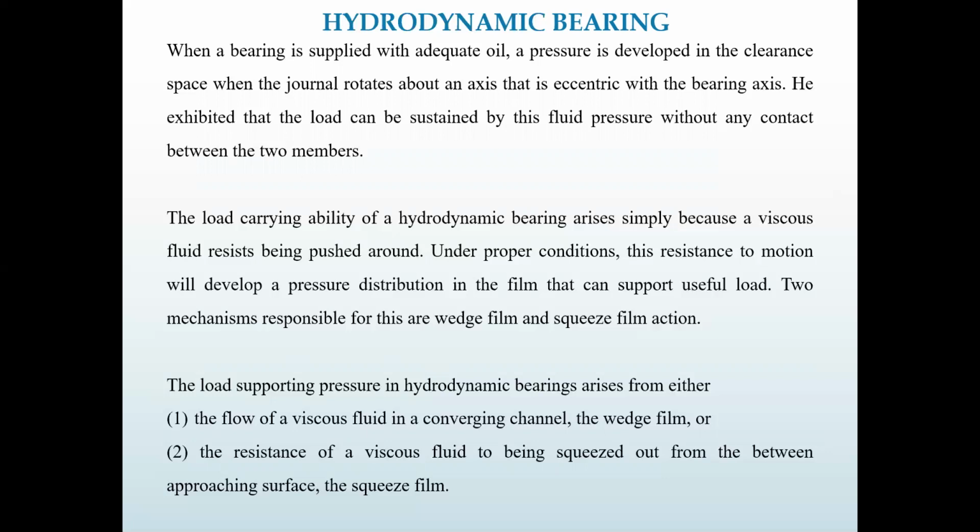The load carrying ability of a hydrodynamic bearing arises simply because viscous fluid resists being pushed around under the proper conditions. This resistance to movement develops a pressure distribution in the film that can support a useful load. Two mechanisms are responsible for this: wedge film and squeeze film action.